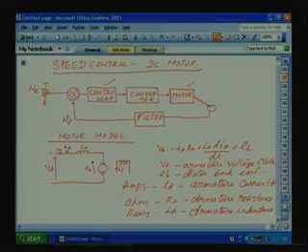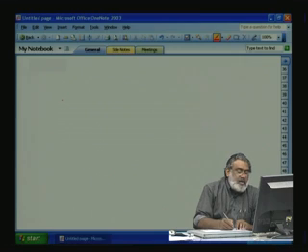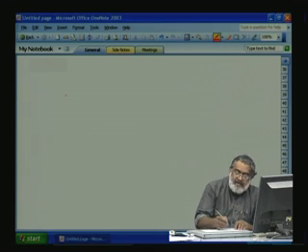Okay. Now, let us write down the equation between VA input and the motor parameters. Now, we are basically controlling the speed. So, in the previous equation, speed we have not brought in. So, here we have to bring the torque. So, the driving torque which is supplied from the input power divided by speed.